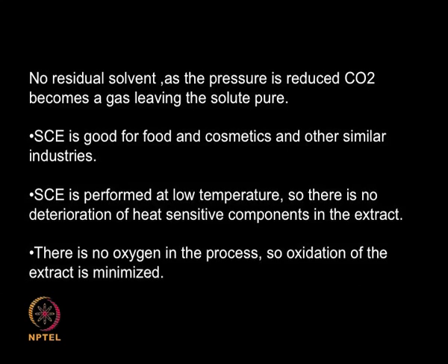Main advantage here is I can reduce the pressure and convert the supercritical carbon dioxide into the gas. So there is no residual solvent left behind with the solute, so the solute will be 100% pure. So it is good for food and cosmetics and other similar industries.